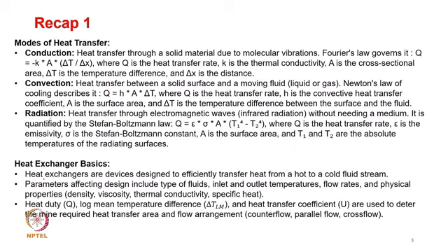Convection is nothing but the heat transfer between a solid surface and a moving fluid, liquid or gas. Here the governing equation is the Newton law of cooling, which says Q equals h A delta T, where Q is the heat transfer, h is the convective heat transfer coefficient, A is the area, and delta T is the temperature difference.